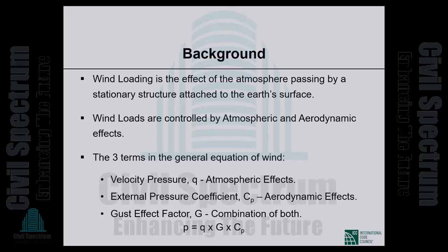But for now, P is equal to velocity pressure Q multiplied by the gust effect factor G multiplied by the external pressure coefficient C sub P.